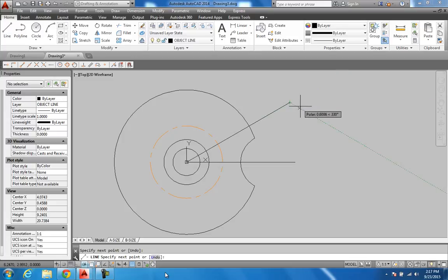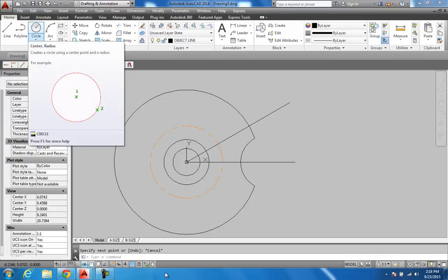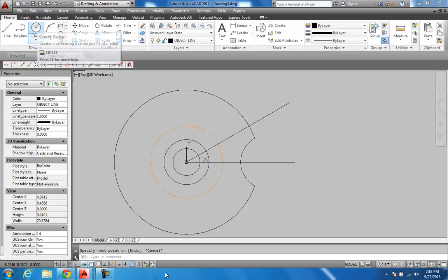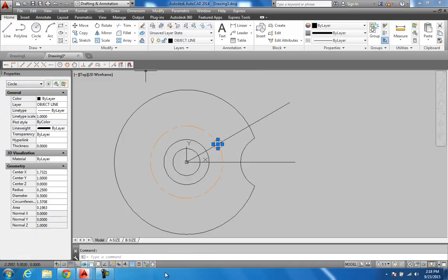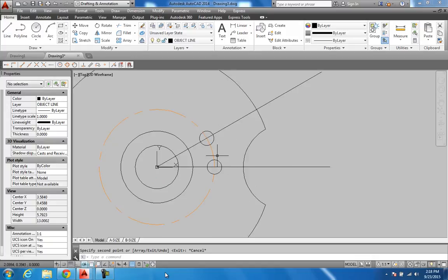You just click on it, and it looks like from this going around through here, at this point I've got like a half-inch slot in there. So I'm going to click on this, come to this point, and it's a half-inch diameter. It's D for diameter, half-inch. Boom. Grab that to copy, catch it with that base point, bring it down there. Just like that. And I might not need all of this.